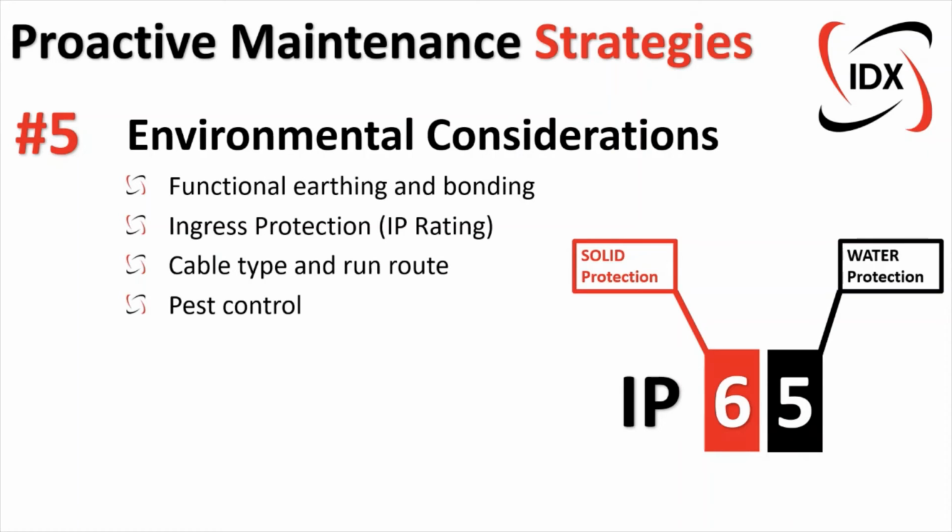And a point I haven't listed here that comes to mind as well is rear panels that are installed within the field that have IP20 devices installed on them. It's very important to ensure that those rear panels are always closed and that they are properly sealed according to their IP rating, as things like coal dust, other types of dust and moisture can severely damage devices, and that can often be a very difficult problem to identify throughout the network.